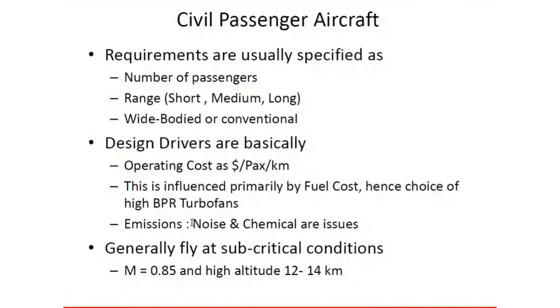You will not get much NOx emissions because most engines are burned at a lower temperature just to prevent the turbines from being destroyed. So there is less chance of that, but you're dumping carbon monoxide and carbon dioxide at the very high altitude where you are flying. So the pollution from aircraft is a significant thing which most aircraft manufacturers are now looking to control.